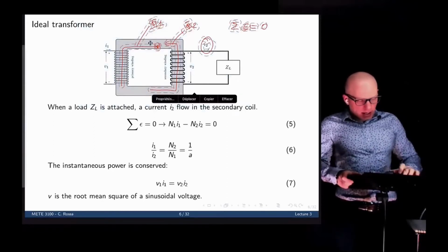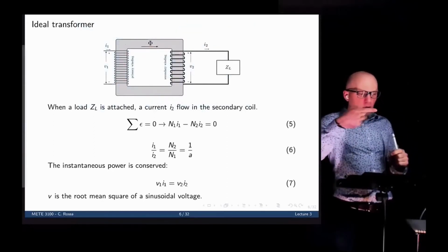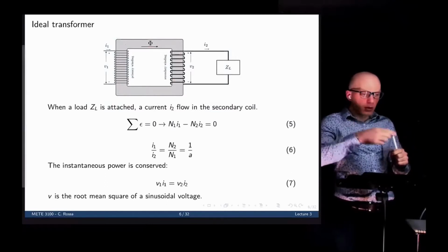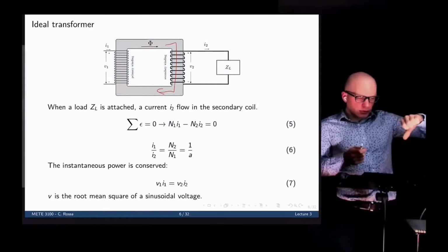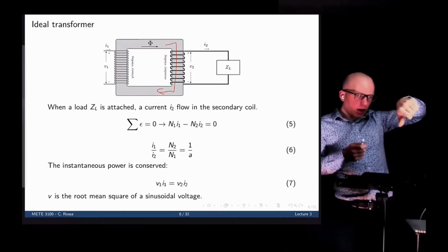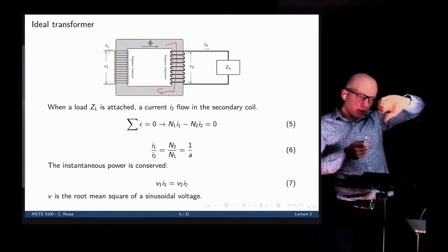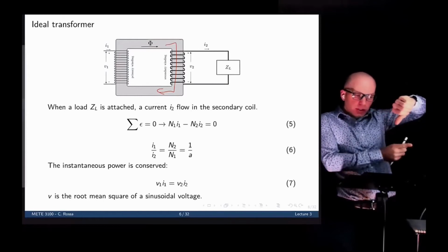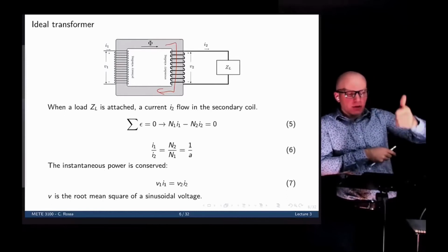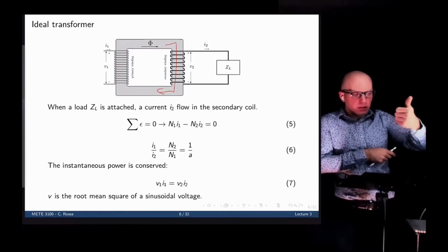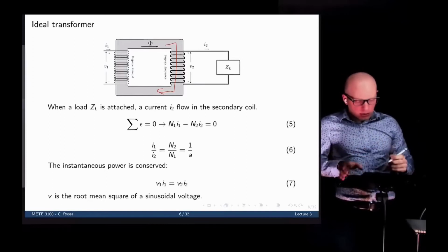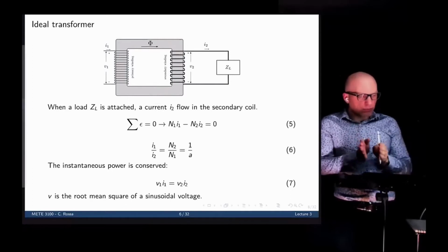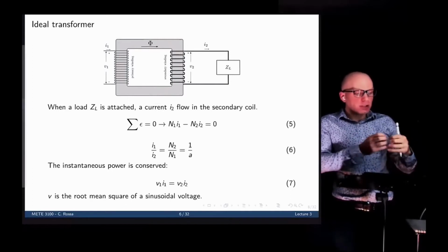This is very important because that gives us the direction of the output current. Let's look at this diagram once again. If the magnetic flux goes that way, going like that, so goes downwards, in this case, the induced current on the other side must be creating a magnetic flux that points up, which means that it must be turning counterclockwise, right? So Lenz's law gives the direction of the output current.